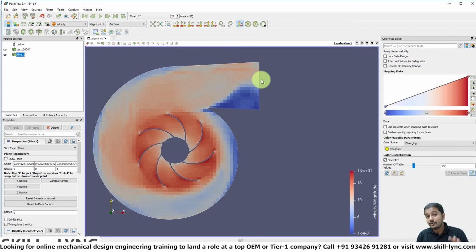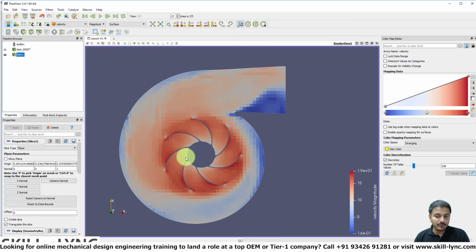Now, the reason why we ended up doing this simulation is to make this important point. Whenever you are situating boundaries, make sure that you put them in a location where the flow is not reversing or recirculating. Alright, so this flow pattern looks okay to me. You can see that away from the impeller, that is where the maximum velocity occurs, because the linear tangential velocity in that area is going to be r times omega, and since r is maximum at the tip of the impellers, that is where the maximum velocity is going to be.